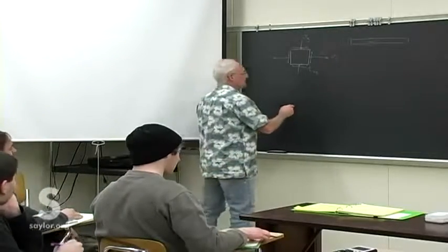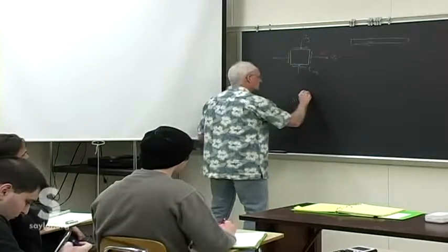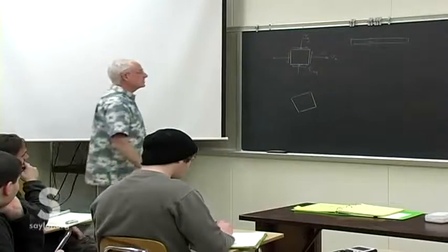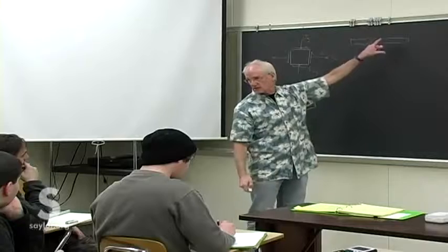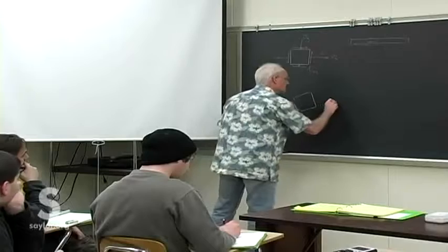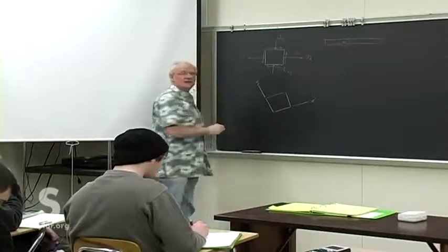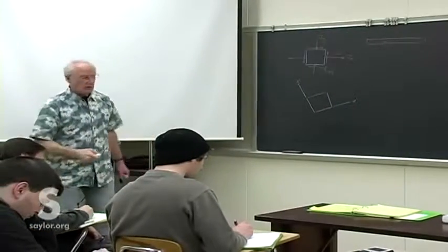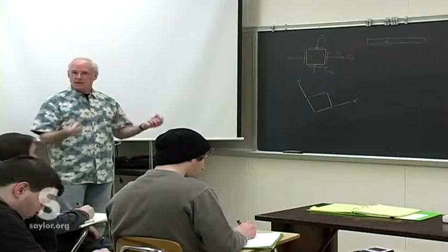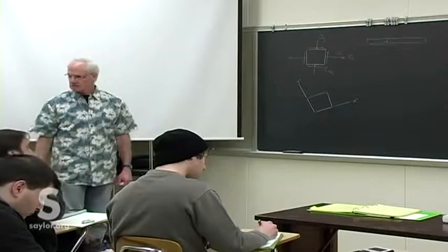But what we were looking at, starting with Mohr circle, the whole idea, Mohr circle is just one way to look at everything, is if we take exactly the same situation, the loading doesn't change, the object doesn't change, nothing changes over here. All we're doing is looking at it at a slightly different angle, because it's no different than in Physics 1 when we get a particular force in a problem, and then we pick a direction for the coordinate axes, and then we break the force into its component directions.